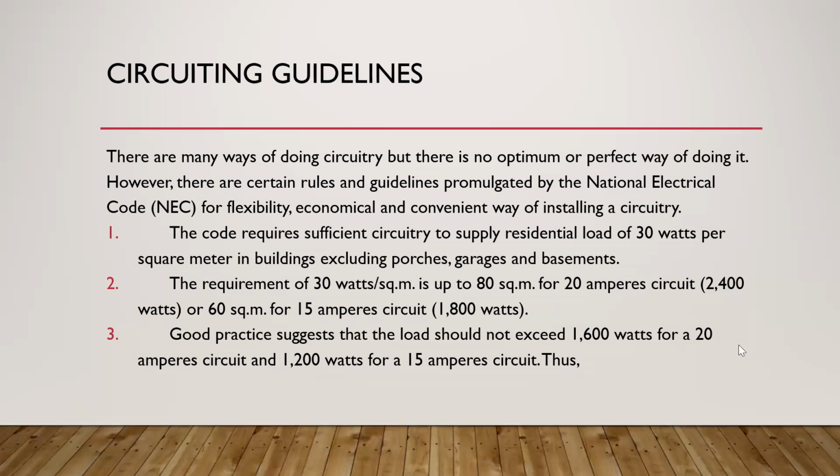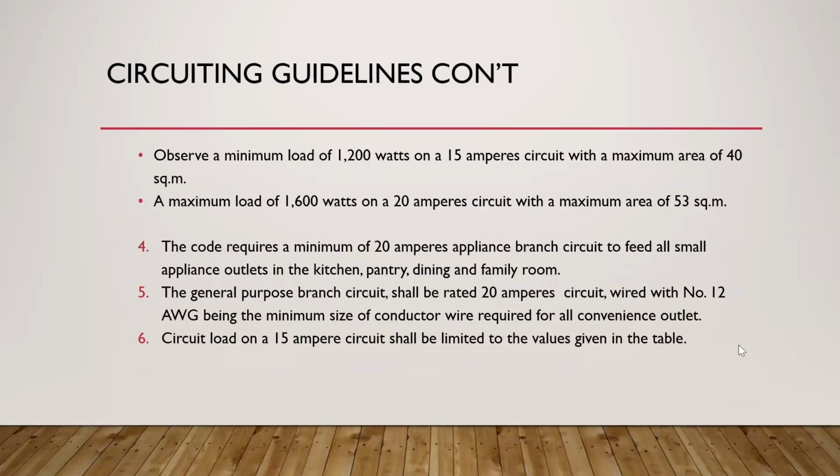na ito. Thus, we will observe a minimum load of 1,200 watts doon sa ating 15 ampere circuit with a maximum area of 40 square meter. And then, thus, a maximum load of 1,600 watts doon sa ating 20 amperes with a maximum area of 50 square meter. Okay.